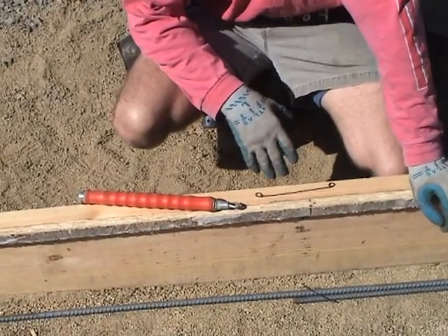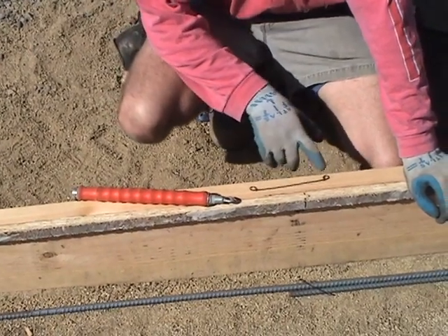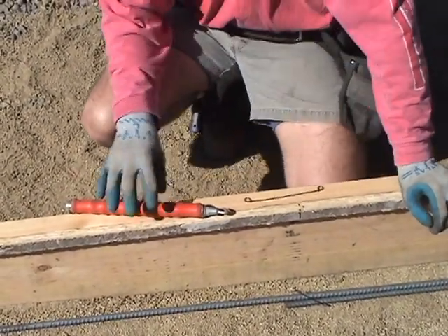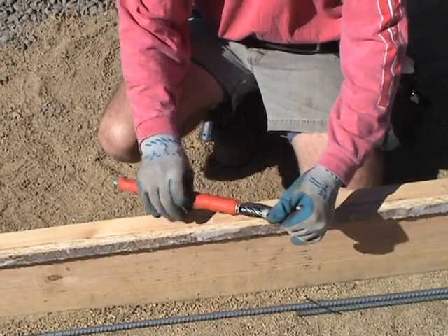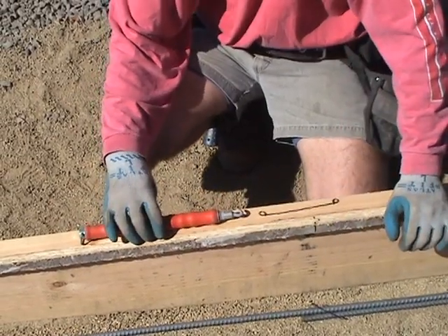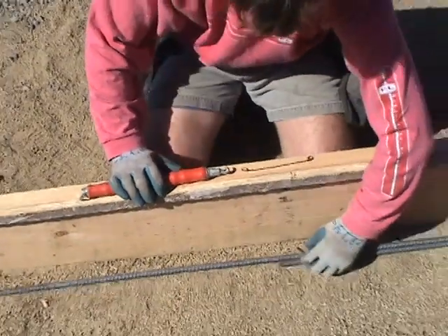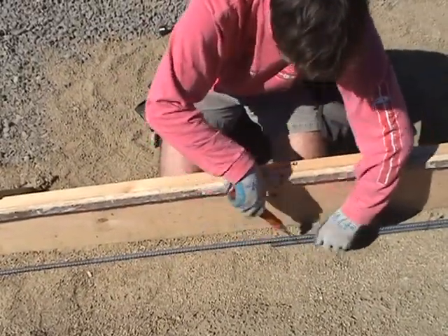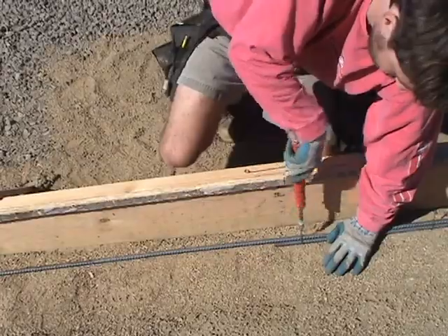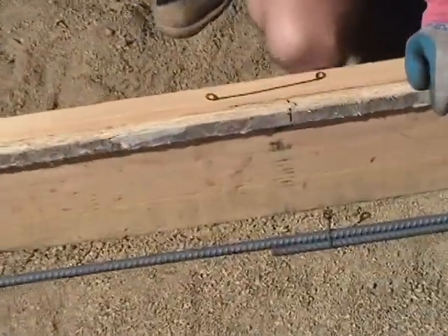So for attaching the loose ends of the rebar together, they make a wire with knotted ends and a puller. And this puller swivels out as it pulls and it twists the wires together. So you take the wire, bend it underneath the rebar, place your hooks and pull, and you're attached.